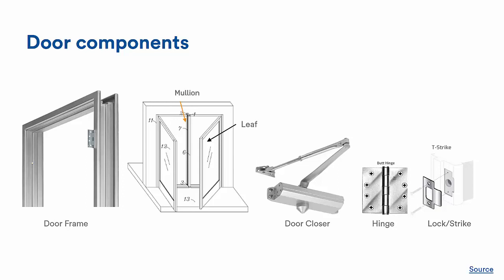One of the most important items of an access control door is the closer, as you want the door to close and lock after entry. So the closer will provide pull to close the door automatically unless the entrance is, of course, obstructed. And we'll cover the electrified access control door components like electric strikes, mag locks, request exits, and door contacts in the next couple of slides.